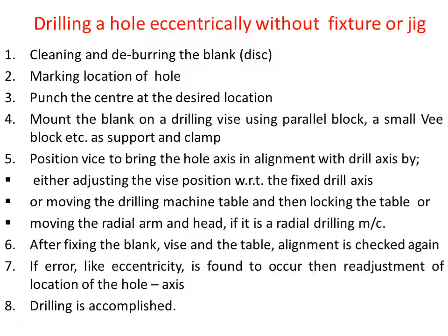First, we have to clean and deburr the edges of the blank before accommodating the piece onto the machine. Then we have to mark the location of the hole. First, we have to find the center of the disc because the axis is not marked. So first we have to locate the center of the disc.